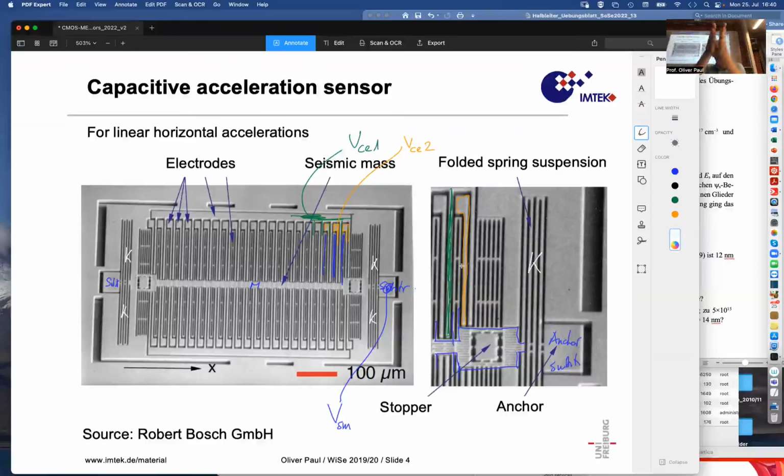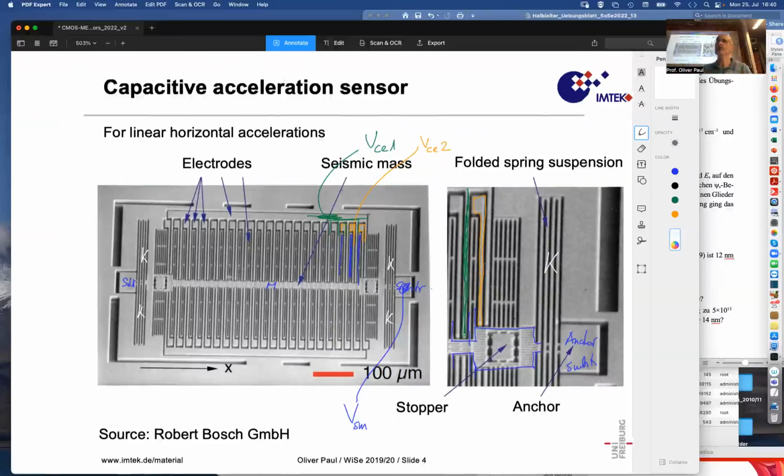Because the film of air between these plates is squeezed, and that causes viscous energy losses, which correspond to the damper. So the dampers are everywhere. Yeah? So I don't expect that Bosch is evacuating their package in order to make it as high Q as possible. Yeah? Because they want a certain time constant.